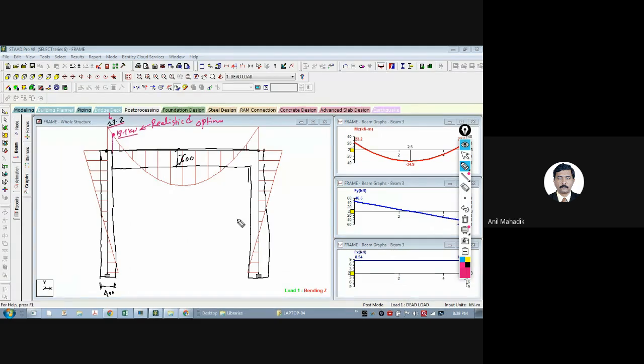See, we are not trying to compare Staad and ETABS in terms of advantages and disadvantages, because every software has its own specialty. But if you ask me, what I like in ETABS is that it gives the results at the face and they are very optimum. That is why the steel quantity required often comes out less. That is the first point. And the second point, I can model the slab in ETABS effectively. In Staad, modeling a slab is very difficult. Rather, we don't do it. So that is the advantage I generally have, ETABS has more advantages.